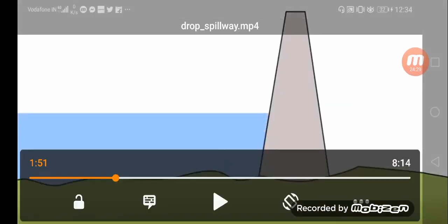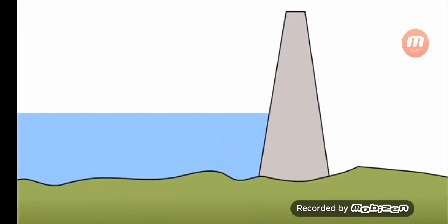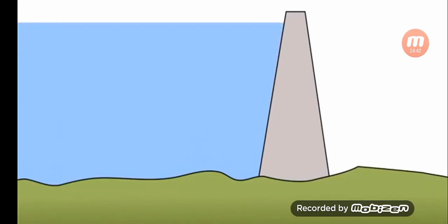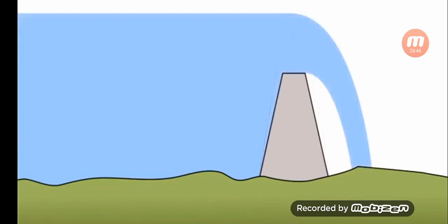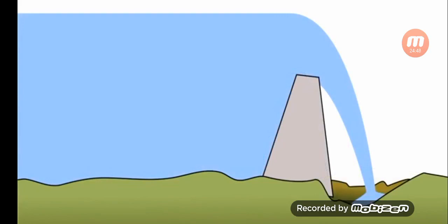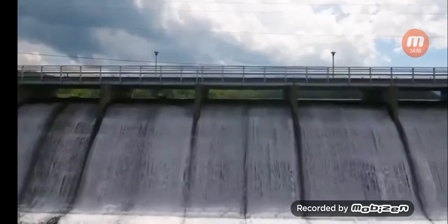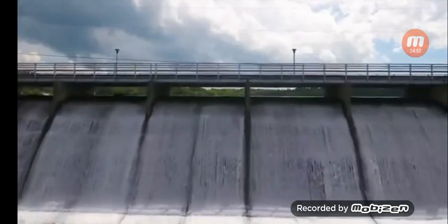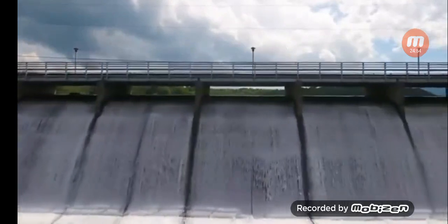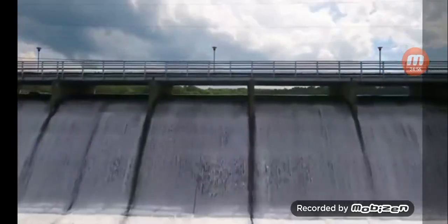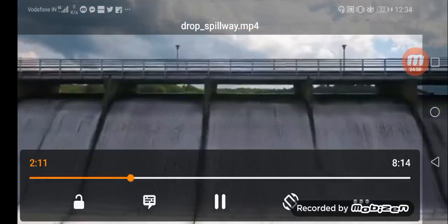It's too expensive. You can see this is the dam construction. If the water level exceeds the optimum level, the dam overflows. If we build a dam so tall that it can store the entirety of this flood, on the other hand, we can't just let the flood overtop the dam because flowing water can damage and destroy the structure. So in most cases, dams are designed with at least one spillway, a structure that can safely discharge floodwaters without causing injury or deterioration to the dam.